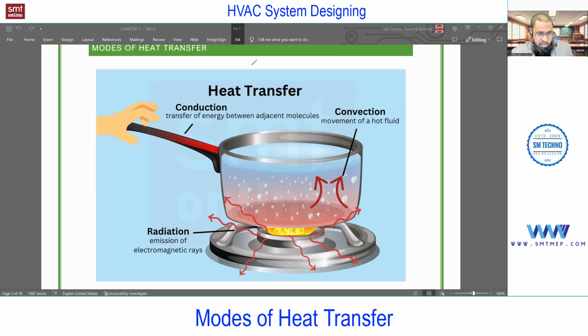So heat gain through ventilation is due to convection. Similarly, when the refrigerant is flowing inside the copper tubes in the vapor compression cycle, that also comes under convection. Finally there is conduction also, because the copper pipe gets heated up and heat will transfer, but inside, the fluid is running. So if the fluid is responsible for transferring the heat, that comes under convection. Okay, we'll discuss more about this. At this level, try to understand just simple conduction, convection, and radiation. Conduction in short is heat transfer in solids, and convection in fluids.